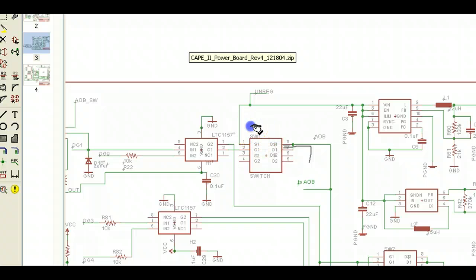Think of that as just a plain old switch. It's actually a solid state switch. It supplies power to what we call the unregulated bus. So when this switch is energized, we now have the solar panels connected to the satellite bus we call the unregulated bus, and if the battery switches are closed, it also puts the batteries on this bus.